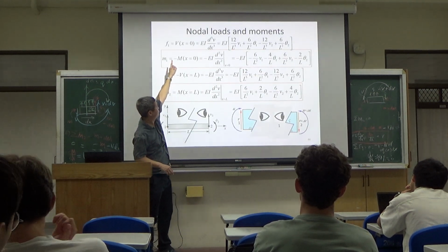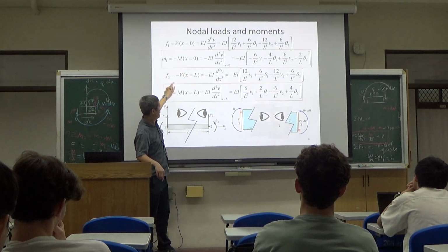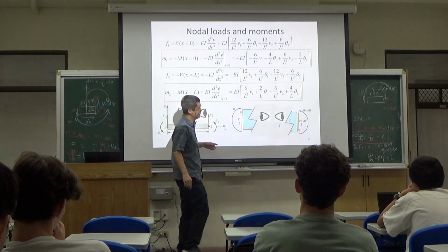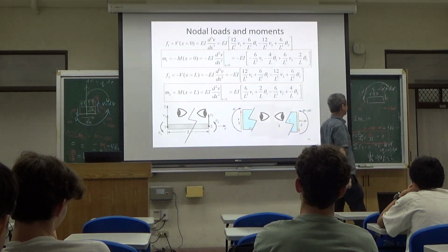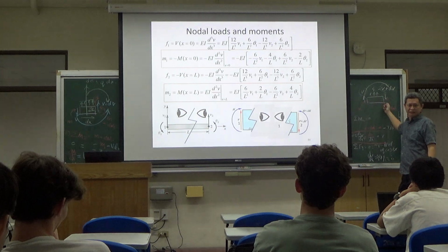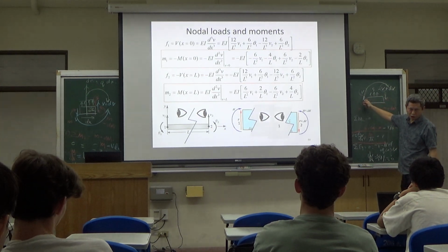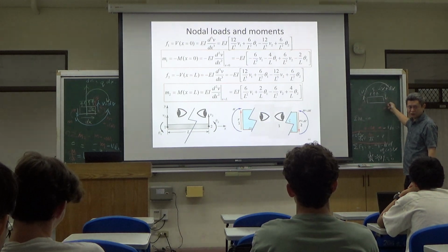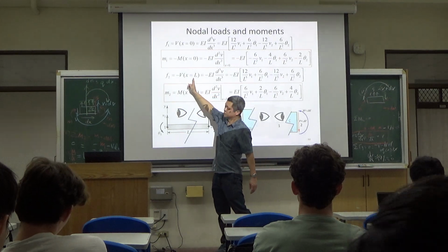This first is the vertical force upward on the left hand side, and then next, how about the vertical force on the right hand side? You see why it's negative? Look at my convention here. My left hand force is upward positive. My vertical shear force on the right hand side is downward positive. See it?